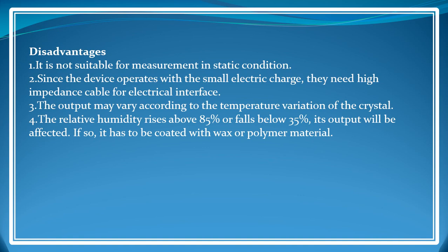The output may vary according to the temperature variation of the crystal, so it's important to fix the temperature. If the relative humidity rises above 85% or falls below 35%, its output will be affected. So we have to manage its humidity also. So we coat it with wax or polymer materials.